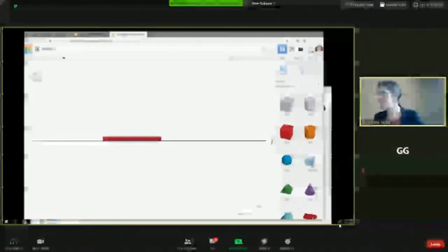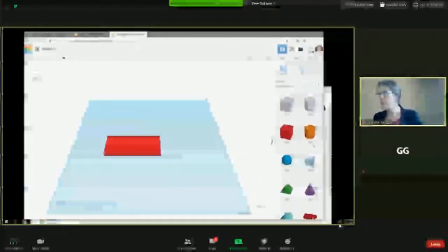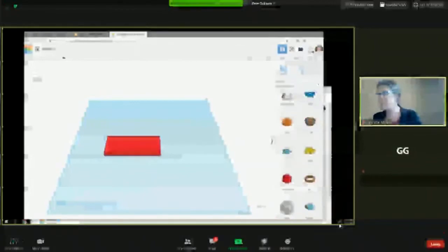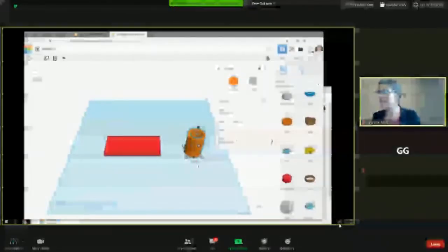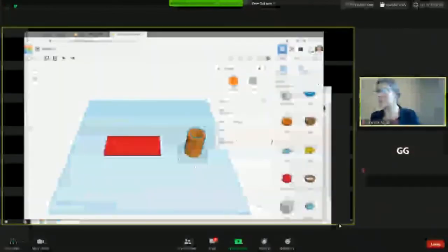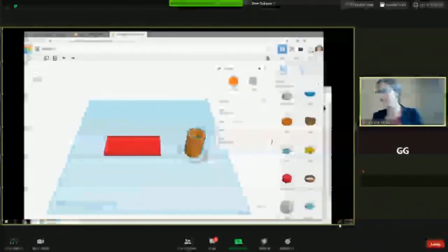All right, we're now going to go down to another object and grab a tube. Just click on it, left click, mouse drag. We want this to be the same dimensions as our keychain, so we're going to make this 30 by 30. You can see I click on the arrows. I should have mentioned this really quick. These bottom arrows let you rotate your objects in the same plane, which we don't really need to worry about yet, or you can tilt them. So again, a lot of interface to work with.